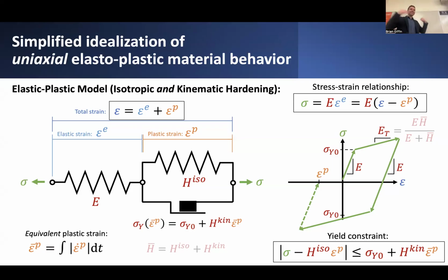And it's the strain that you would see if you were to try to remove all of the stress that you were applying to this whole assembly and allow this elastic spring to compress back down to effectively zero elastic strain. You might still see that there's some residual strain built into this assembly that's directly proportional to this plastic strain. So that's the idea. We've posed that we can decompose the strain in this way into an elastic part and a plastic part. And furthermore, we suppose that the actual perceived stress in this whole assembly is just directly proportional to precisely the stress in either one of these two subassembly elements.